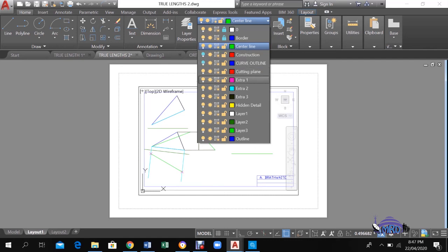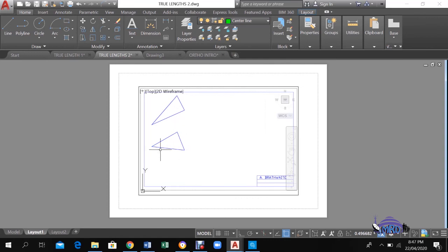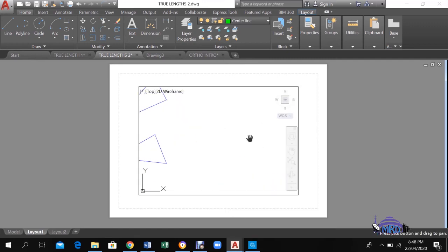So in that regard, we end up with a situation where there is no real representation in the vertical or horizontal plane. And with that in mind, we then will have to determine the true length of the sides of the lamina as represented here, and then use that information to produce a shape that is representative of that